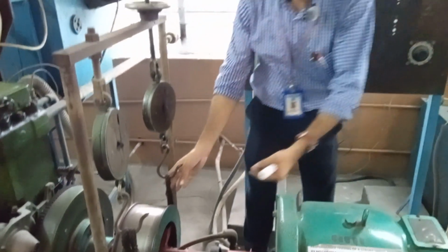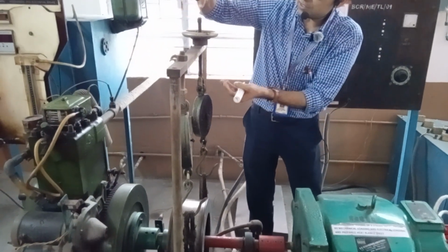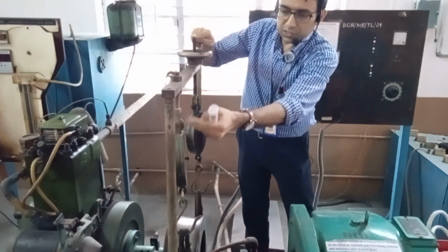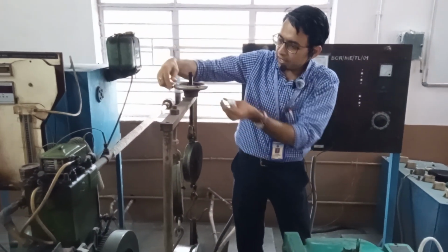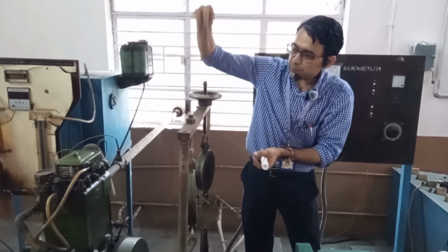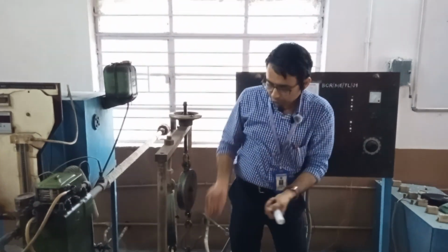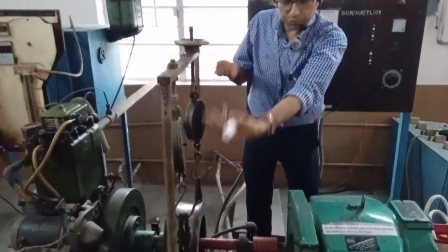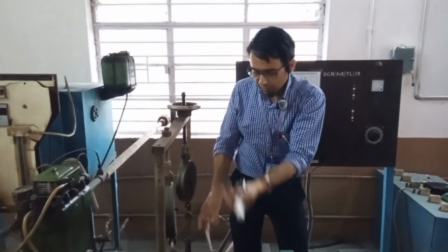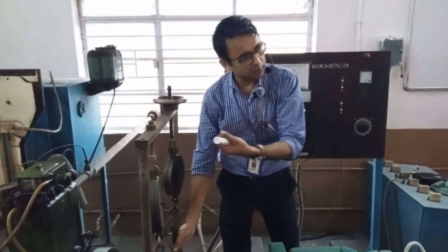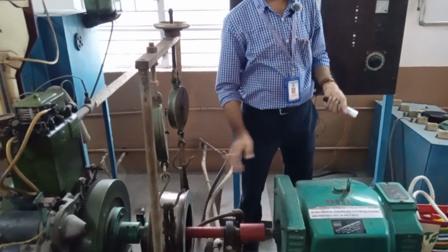Okay, so what will happen, there is a fixed one, so this length will decrease as this comes up. The total length is fixed. As I rotate the wheel, this part will come up, this will remain here, and therefore the length remaining within this part will be reduced, so it will be tightened and grip the brake drum.